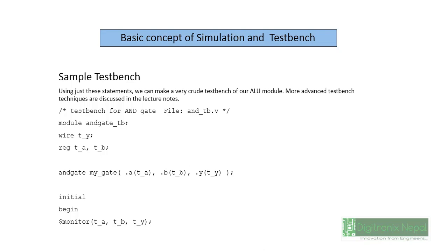We also designed the AND gate in the previous lab, that is lab 1, and in this upcoming lab 2.1, we are going to design that AND gate again, create a simulation test bench ourselves by utilizing this source, and generate the waveform for that AND gate. So let's see the sample test bench for the AND gate.